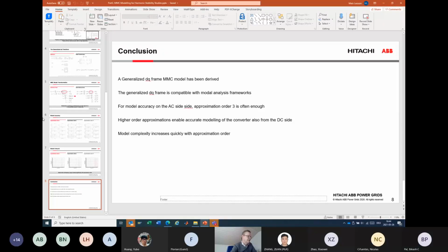Okay. And that can sometimes give rise to problems. For example, I got some cable data from the Danish TSO. So they have a lot of cables on the high voltage network. And when you have them on the high voltage network, often you have this flat formation cable. You don't have all three phases in the same cable. You have one cable per phase, and you do not lay them in a symmetrical formation. And that means that the impedance matrices you get are unsymmetrical.